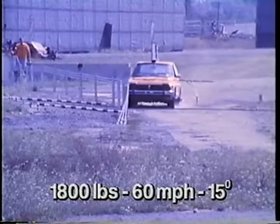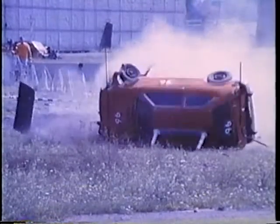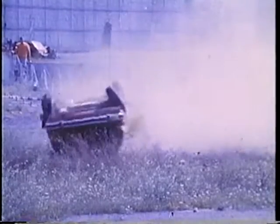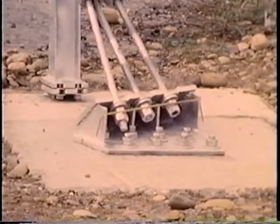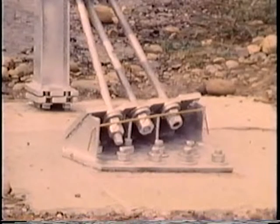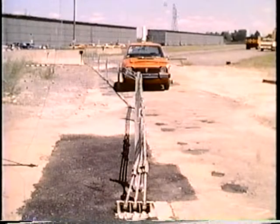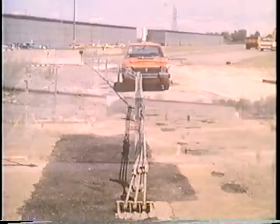When this same problem was recognized for both the standard G1 design and the flange channel post design, the state of New York set out to develop an alternative anchorage. The result is a modified terminal consisting of a concrete anchor, an attachment bracket, and a slip base post. The cables pull free from the slots in the bracket during an impact. The whole anchorage assembly is flared back from the roadway to reduce the chance of a direct collision.